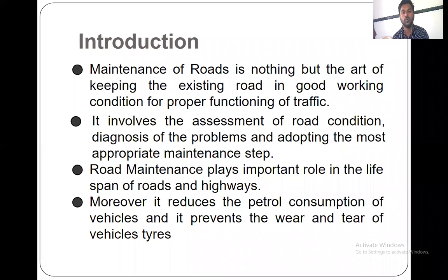It involves the assessment of the road condition, diagnosis of the problem, and adopting the most appropriate maintenance steps. Okay, what are the steps we need to carry out while doing the maintenance? First we need to diagnose the problem. Before going for the remedial measures for that problem, we need to understand the diagnosis. Because suppose there is a patch fault, and we simply apply the broom, apply the coarse aggregates and fill it with the binder material, maybe bitumen or maybe concrete.